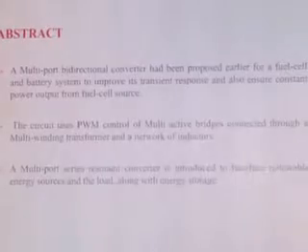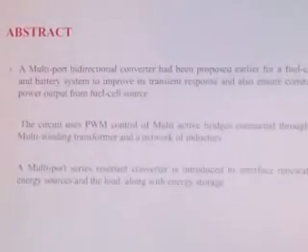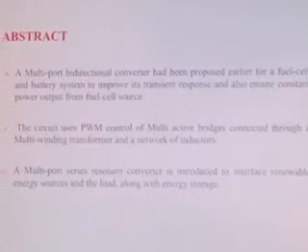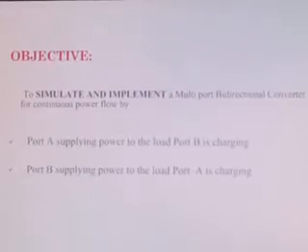the load bidirectionally, that is from source to load as well as from the load side. We are using a multiport bidirectional converter that has been earlier used for a fuel cell and a battery system to improve its transient response and also to ensure constant power output. We are using a PWM control of multi-active bridges.